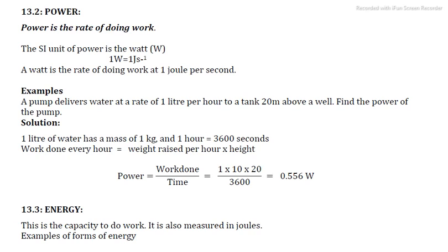Example: we are told that a pump delivers water at a rate of 1 liter per hour to a tank that is 20 meters above a well. We are supposed to find the power of the pump. If you look at the question, we are given the capacity, that is 1 liter, the time, that is 1 hour, and the height, which is 20 meters.